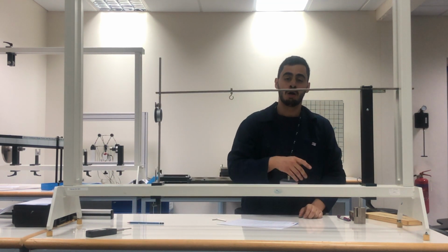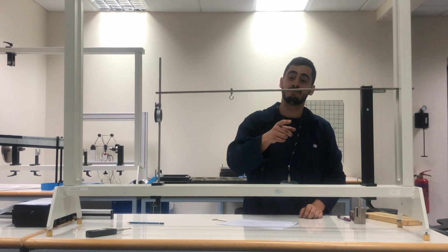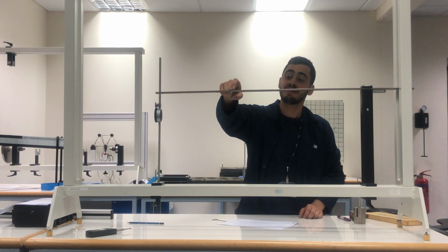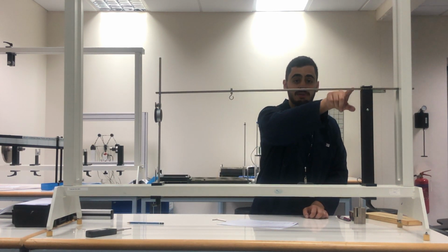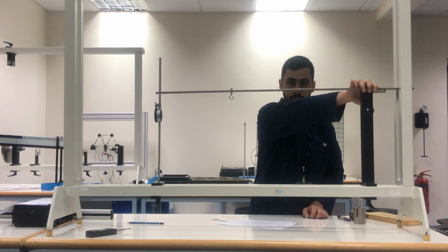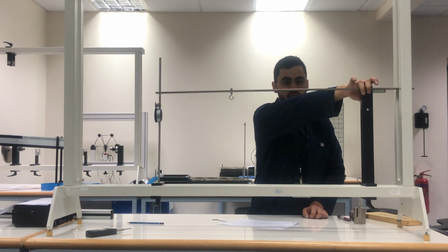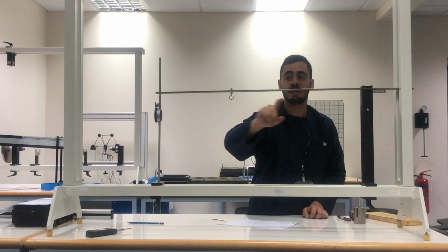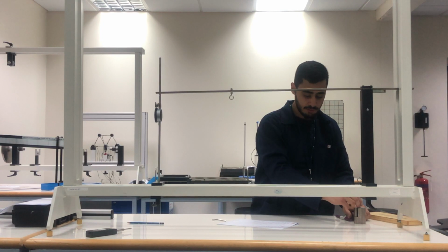Fantastic. Now, also according to your slides, we have calculated the maximum force that I can apply at a distance of 500 millimeters that will generate the maximum allowed moment at the fixed support. We said that this is going to be 100 megapascals, and we found out that the maximum force that I can apply to achieve this 100 megapascals was approximately 24 newtons. So we had to select 3 weights that are smaller than 24, and this is what I have.